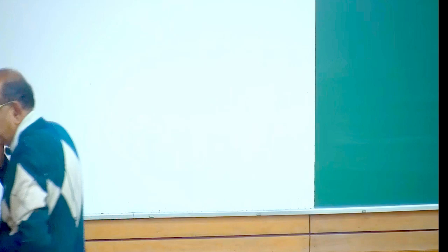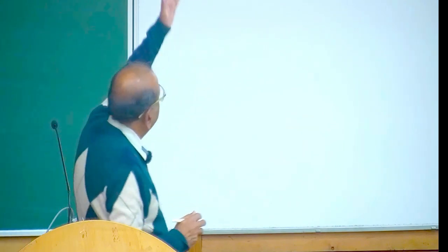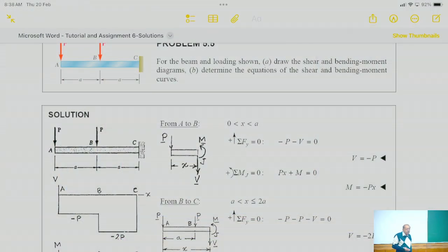Okay. So in problems like this, you have to find the shear force and bending moment diagram. In certain problems it so happens that you have to find the reactions to be able to solve the problem. In others you don't. And if it is a statically indeterminate problem, then you will need chapter 9, you will need deflections to be able to find that reaction. So, for example, a problem like this, if you start, you actually don't need to find the reaction at C to solve the problem.